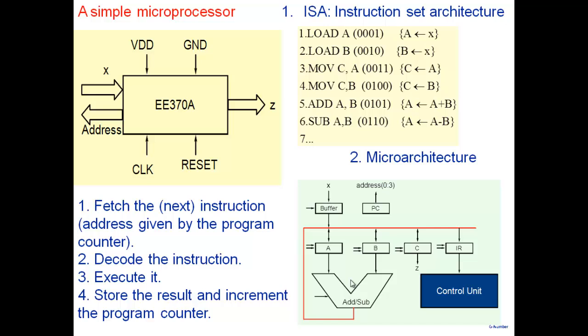Okay? So, in a quest to come up with a general purpose digital system which you can customize for different applications, we have naturally arrived at the concept of a microprocessor, where a microprocessor can execute a set of elementary operations, and the user writes a program, stores it in a memory, and the program tells which instruction to do in which order, and thereby you do the computation that you design.